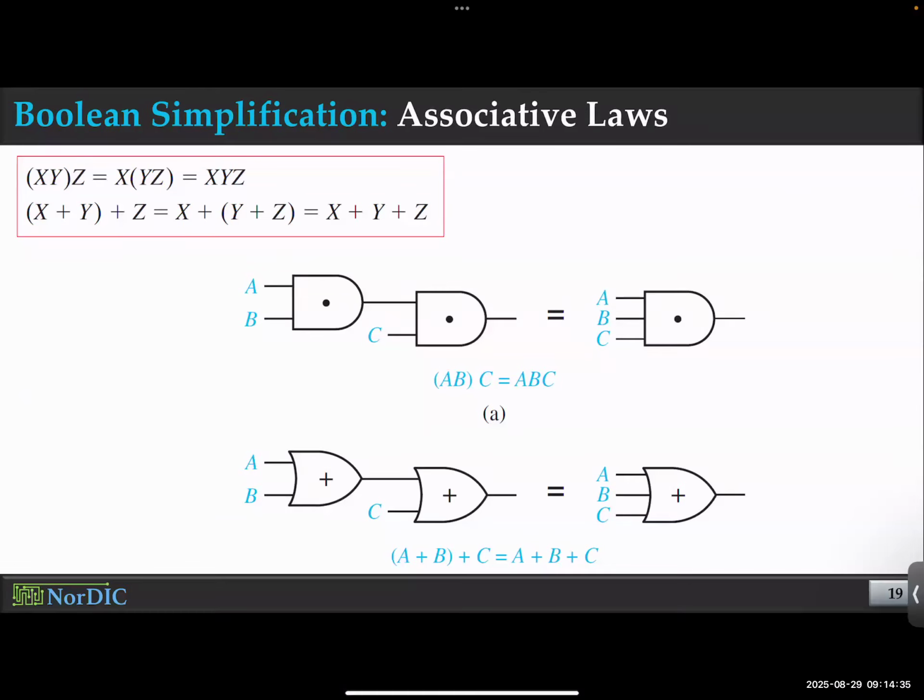And as I told you many times, none of these are done manually today, right? You have software, you have electronic design automation tools that will take care of it. So these are often called synthesis tools. What you do is you code the hardware and you run it through a synthesis tool that basically takes the design that you have in terms of Boolean expressions and then optimizes it into something equivalent. So it will maintain logic equivalence. Are you guys still with me?